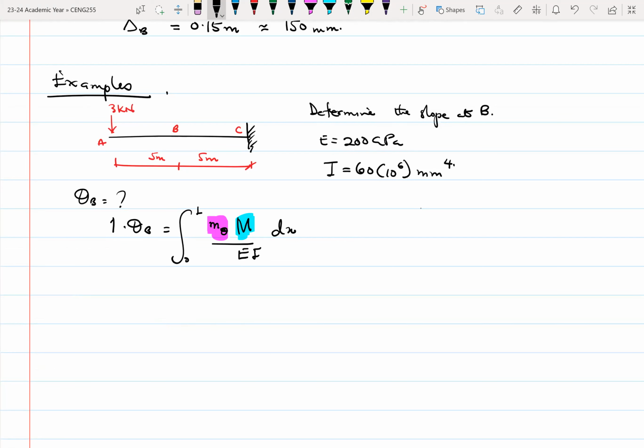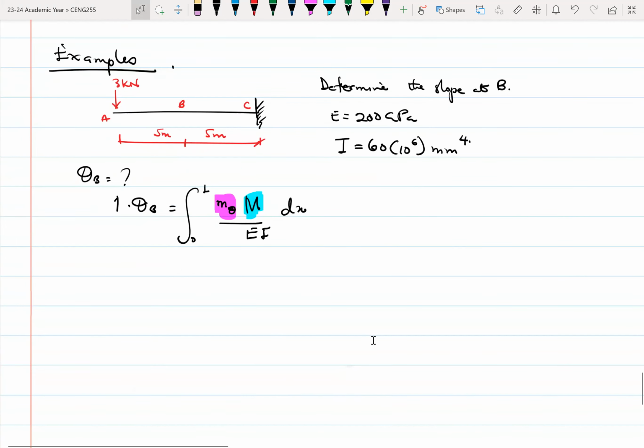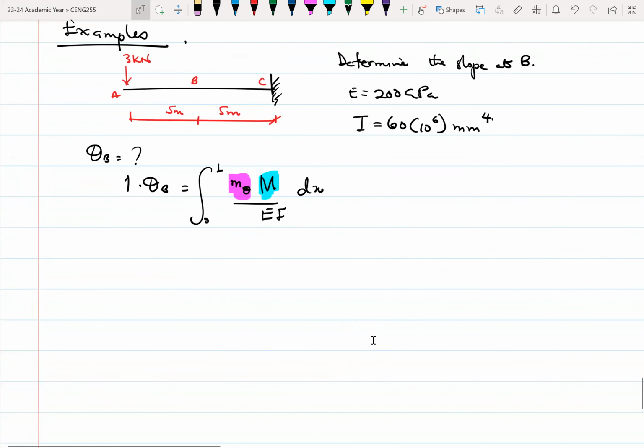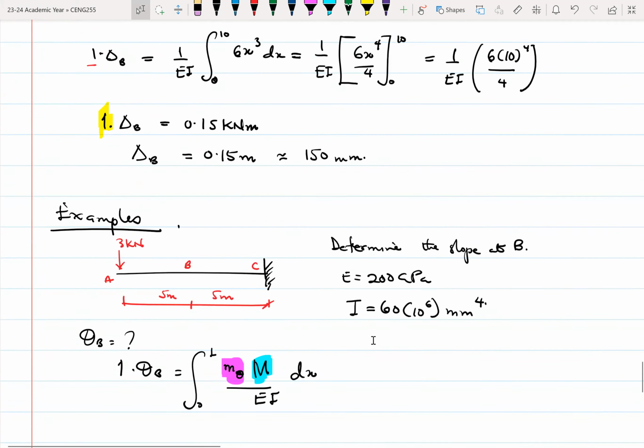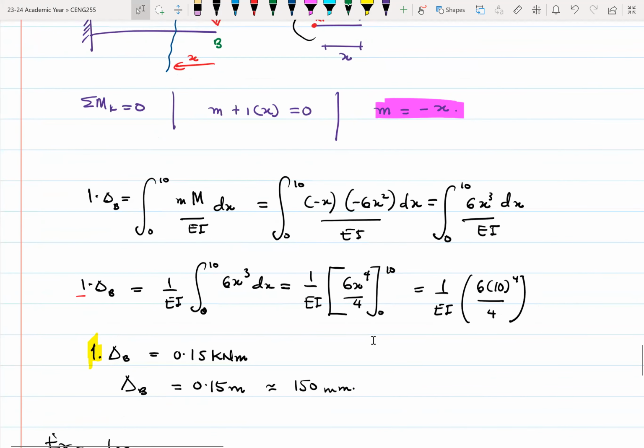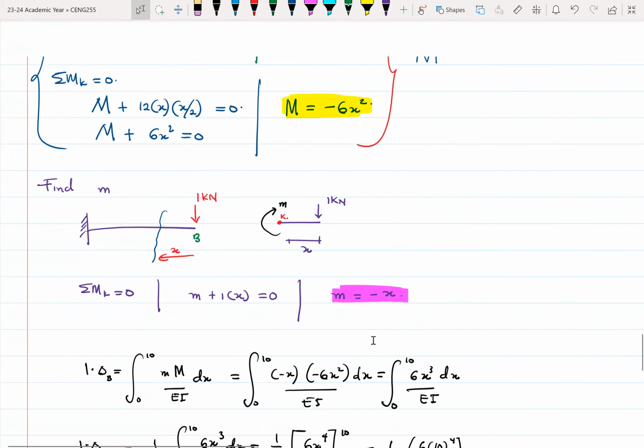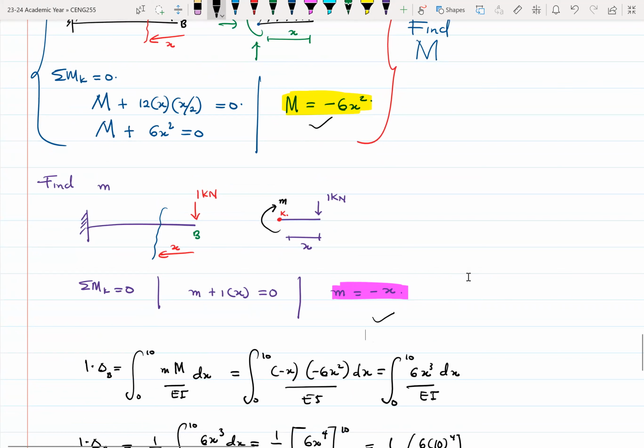So what do we do? So let's start with the real loads. All right, and please take notes. The equations that we wrote earlier, this equation here. Anytime you write an equation, the equation needs to be valid for a certain span, right? Luckily for us, for the first question, the equation was valid for the entire length of the beam. So it made things easier for us. In some cases, equations can only be valid for certain spans or certain regions. So take note of that.